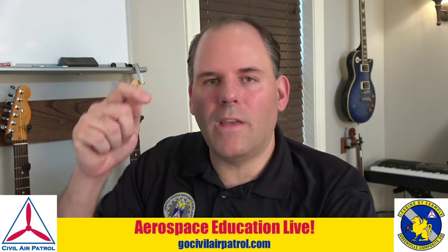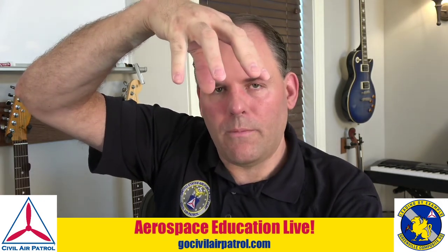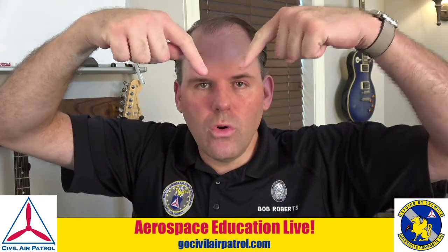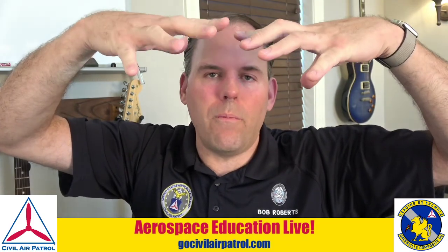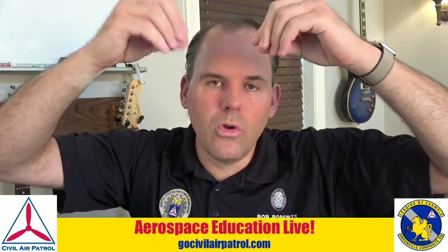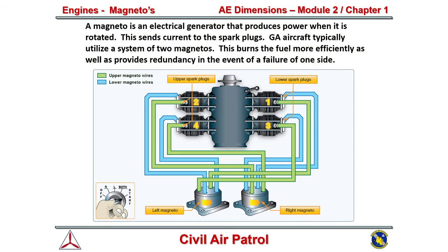The first reason is that if we have a single spark plug, it has one spot to basically burn the fuel. If we have two spark plugs and they're on angles, now we have two areas and a better, smoother distribution of that burning of the gas. That helps our fuel economy. The other thing it does is it allows us to have a left magneto and a right magneto.